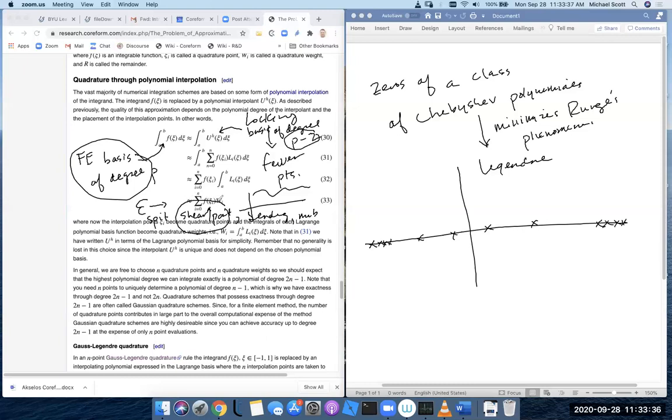So what that's equivalent to is a mixed method where you're integrating certain parts of the strain with a degree p basis, but these locking parts you're integrating with like a p-1 basis. But rather than actually constructing the mixed problem, you do it implicitly through quadrature. That's what reduced quadrature does. It mimics the behavior of mixed problems without having to build the mixed spaces.